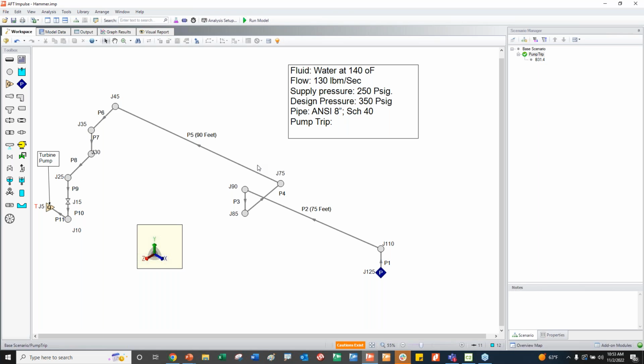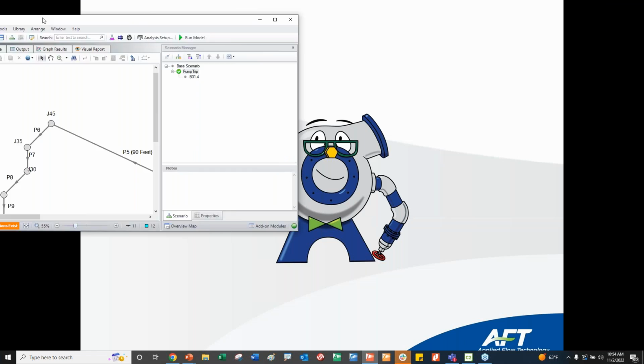They might be going up in a pipe rack, and I want to report to the civil engineers. But again, if there's a hanger here, and since hangers are not dynamic restraints, I want to examine this section because it has very low frequencies, and very low frequencies are easily excited because they require less energy to be excited dynamically and show high movements in the pipe and create high stresses.